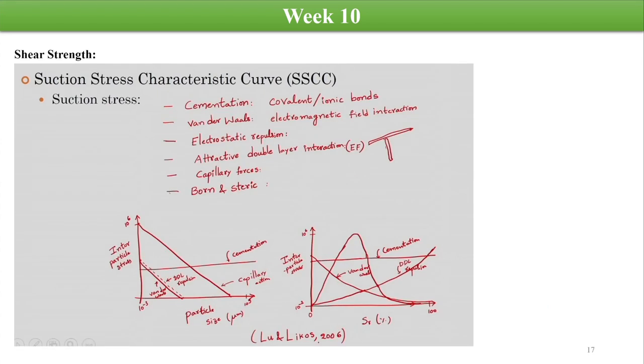Moving further, suction stresses include cementation, van der Waals, electrostatic repulsion, attractive double layer, and capillary, bond and steric forces. If we plot the interparticle stresses against particle size, we see that cementation does not depend on the particle size, but as the particle size increases, the capillary action decreases, because the size of the capillary also increases. Van der Waals forces also decrease as the particle size increases. Similar is the concept for diffuse double layer repulsion.